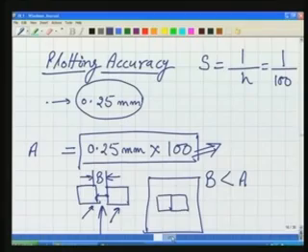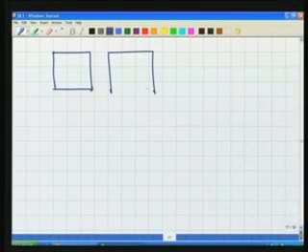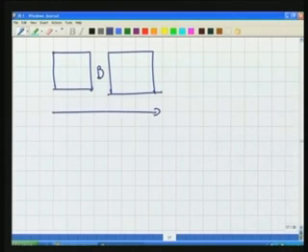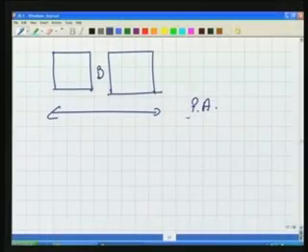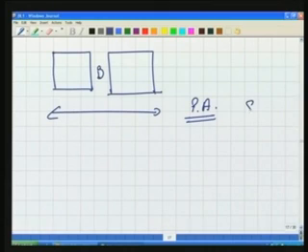Should we measure very accurately in the ground, as in the previous example? Should we measure these two objects, that distance was B, as separate objects there in the ground, or should we measure them as one? Well, the decision is to be taken by your plotting accuracy, what your plotting accuracy is, what your scale is.